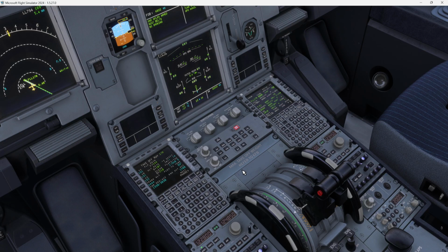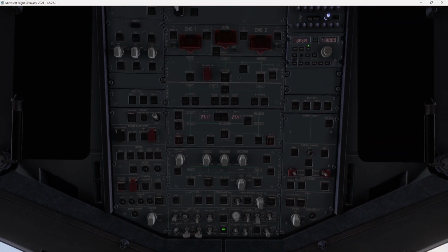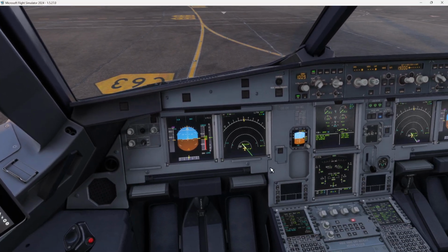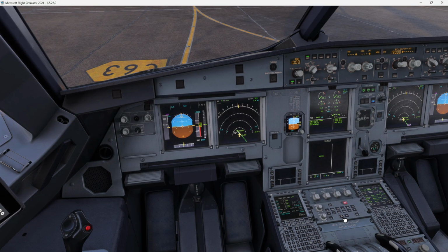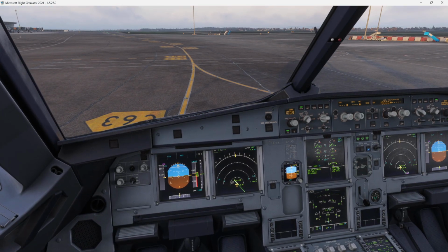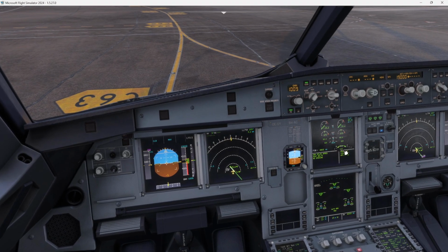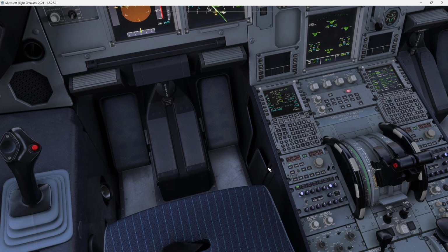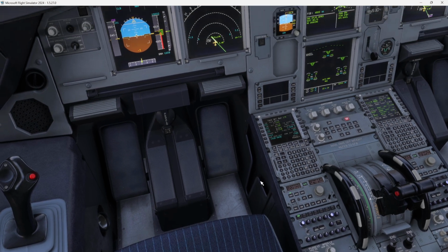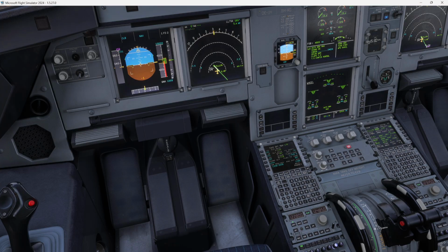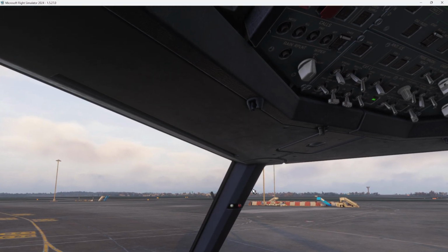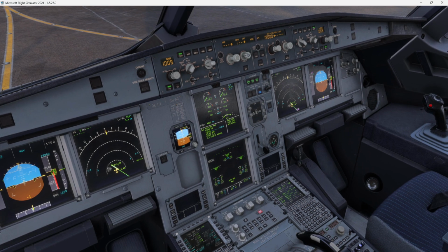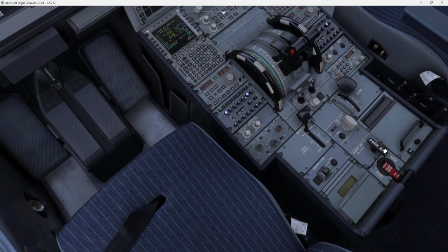After startup checklist, please. Anti-ice are off, ECAM status normal, pitch trim down 0.5, rudder trim neutral. After startup checklist completed. Taxi checklist: flight controls are checked, flap setting 1 plus F, radar predictive windshear on and auto, engine mode selector normal, and ECAM memo takeoff no blue. We are waiting for the cabin, so taxi checklist is completed. Let's notify the cabin and let's taxi.